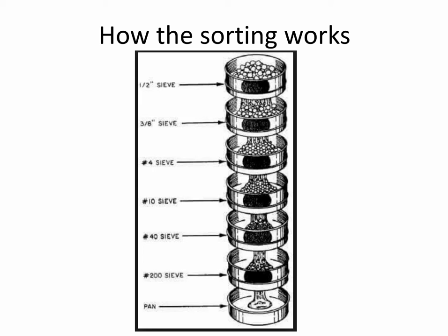So these are not particles that are of interest to us, say in concrete mix or asphalt design. Clays are great for earth dams, for when you're looking for impermeable layers, but they're not great for strength for construction purposes. And normally we wouldn't want anything even below the 100 sieve in any of our mixes.